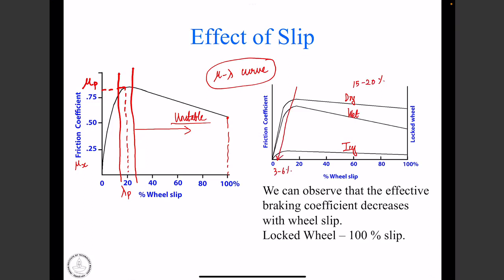Like so, the peak values, and the slip ratio at which the peak values are obtained, also reduce. Now, this brings certain interesting challenges to us, right? So we have essentially converted the problem of avoiding braking to a problem of regulating lambda. Can we regulate lambda around lambda peak?